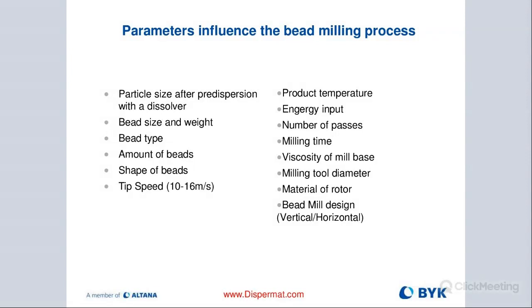The shape of beads, very important. We always want them to be perfectly round, no edges, so they should be really spherical. Again, stay away from cheap, inexpensive beads. We have seen cases where people buy them or get a sample, and then when they order the first lot, the sample looks totally different than the actual lot, and the beads are no longer balanced and round. They now have edges, and they're not ideal for milling.